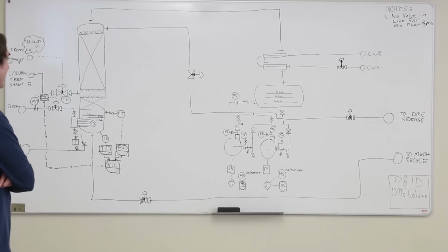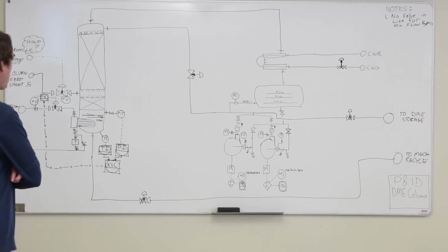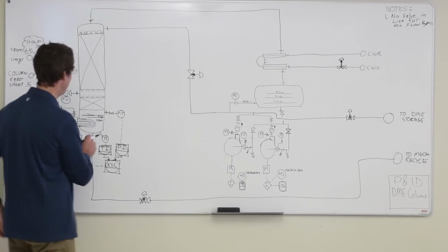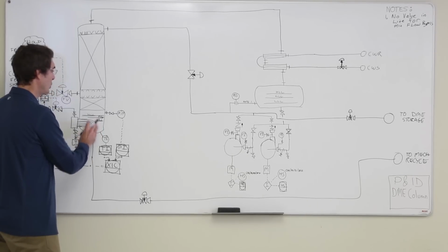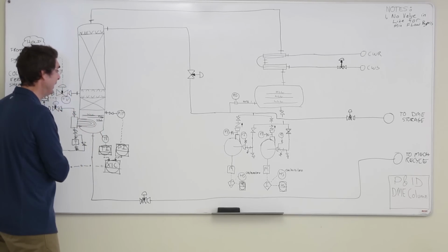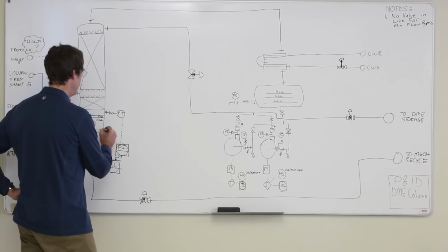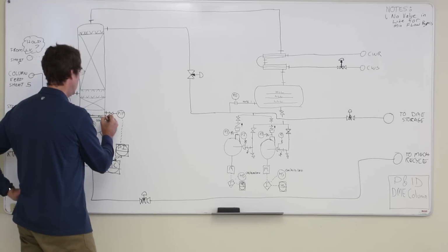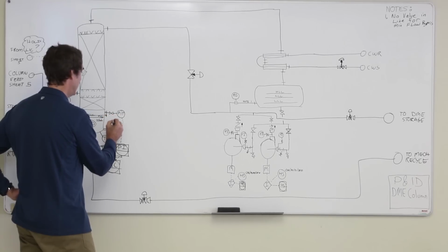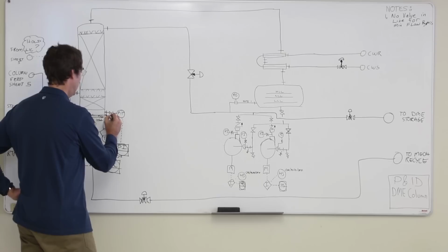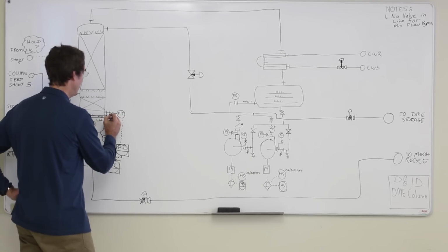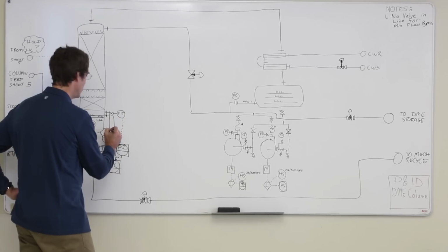Okay, now we've got to get the level control in there. The level control is made complicated by the fact that that swell is going to affect the level transmitter. If we could eliminate that a little bit, that would be a nice thing to do. So one way to do that is to take some nozzles off the side of the tank and build, you can do it either internally or externally, a little stilling well, like this.